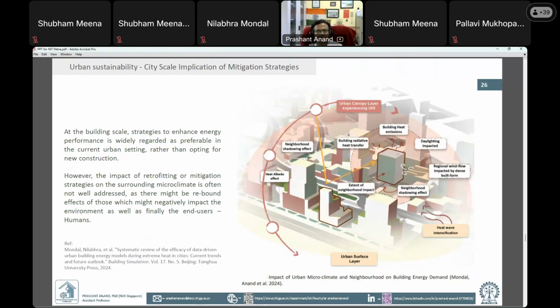What will happen in the case of high-rise and densely populated residential buildings? Because it is high-rise and densely populated, rooftop area is less compared to the total floor area. So the energy generation is only dependent on the area where direct solar radiation is coming, or diffuse radiation, which will give some, but not that high. In that case, converting that building into a zero energy building and running it purely on renewables may not be possible.